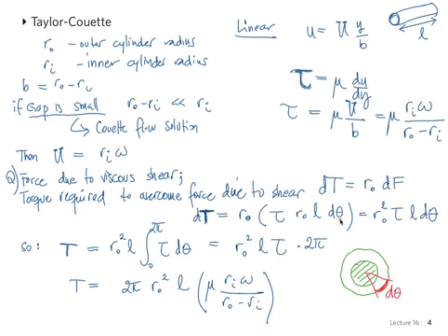And we're using the Couette solution with C equal to 0, assuming that there is no pressure gradient along the cylindrical coordinate here. That's why we have this solution for the velocity, which is only the linear component of Couette flow, if you recall. If you look back at your Couette solution, it's only the linear component. So this one is already taking into account that dP/dx is equal to 0. So the two assumptions are circular to linear and dP/dx is 0.